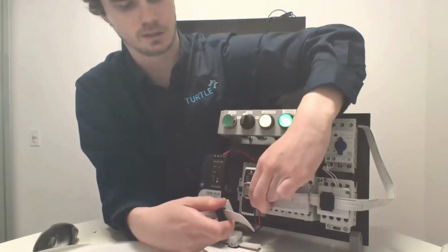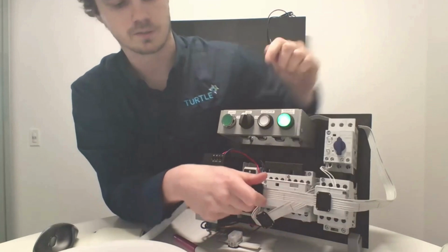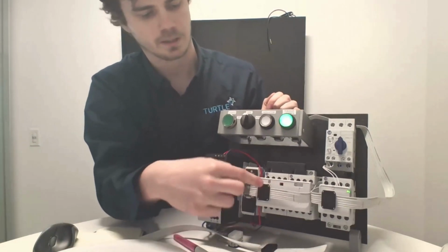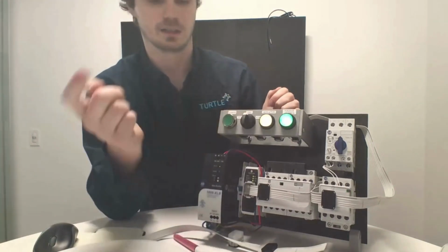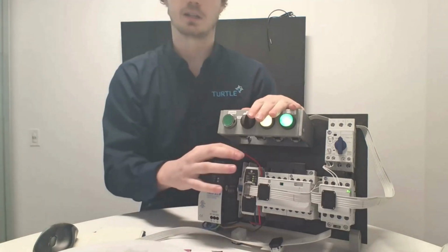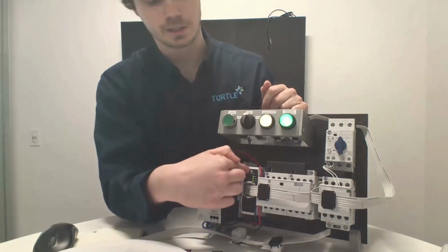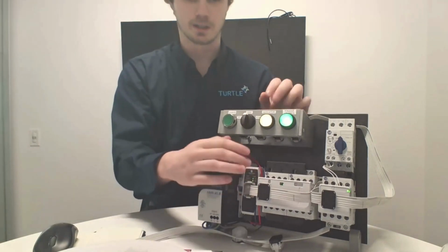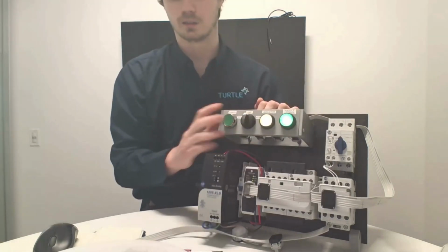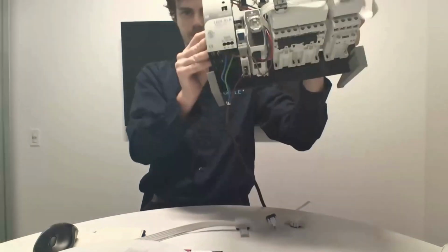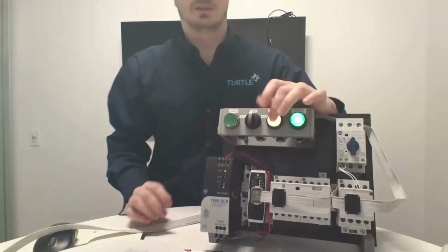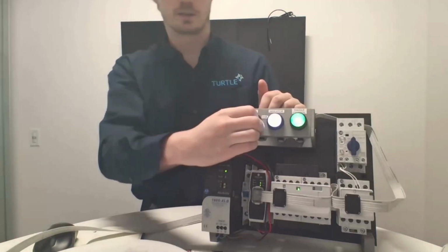This device is going to go into whatever is available, and you can put it in there. But right now, I want that, so you can see that indicator turn on and off. These devices here are communicating peer-to-peer. So this gateway is holding the program that I wrote in Studio 5000. So all these devices are acting locally, and there's no PLC in the system. This is just a power cable. And once again, you can still see all these devices are working fine.